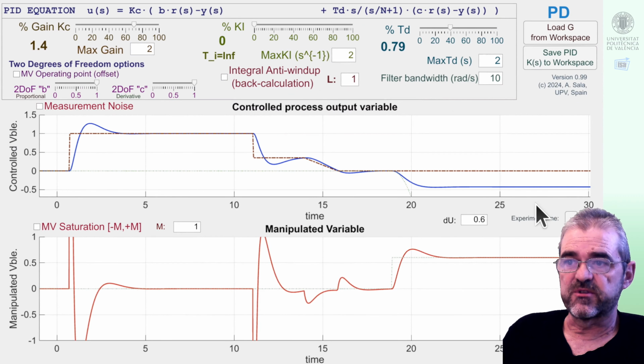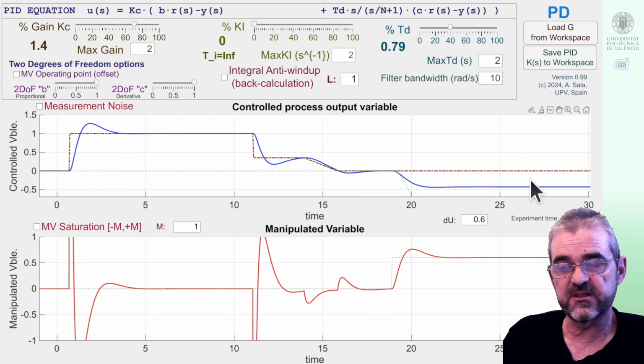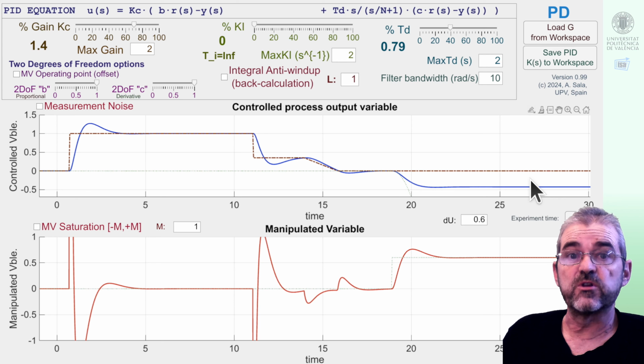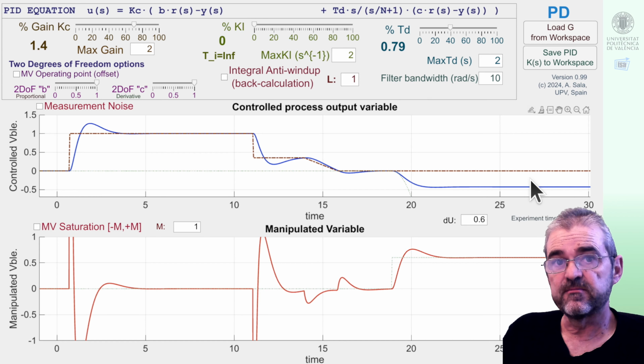Well, input disturbances cannot be directly measured. We don't have a sensor for them, otherwise we would carry out what is called feed-forward control, but in this case, with feedback only, we cannot measure them, and also we don't know what their amplitude will be. I mean, we can specify to the user some ranges of set points and the speed of variation of the set point, and prescribe that in my contract. But disturbances will be whatever they wish to be.